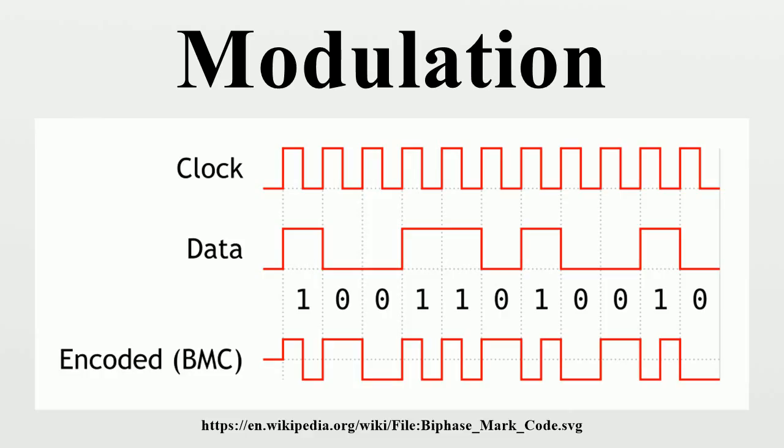Indeed, MSK is a particular case of the subfamily of CPM known as continuous phase frequency shift keying, which is defined by a rectangular frequency pulse of one symbol time duration.